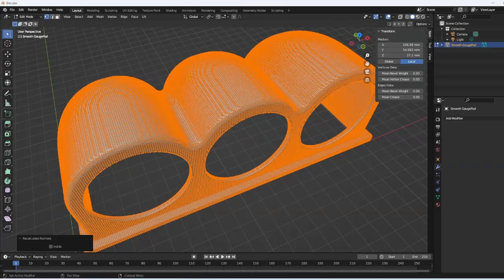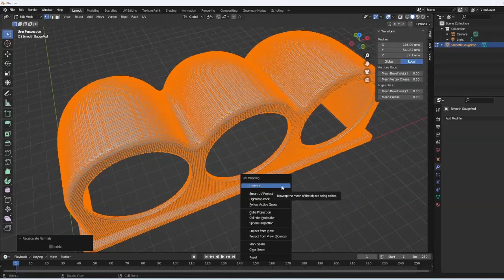And then the next step is we need to UV unwrap everything, basically. So the way that we're going to apply this texture is all of these nodes are going to be unwrapped, as if we are going to place this entire thing onto a flat piece of paper, and we're going to color it in with this texture. There are special algorithms that Blender will apply. We don't actually have to know them. All you have to do is know that once you're in this mode and you've selected everything by pressing A, you press the letter U and you go Smart UV Project.